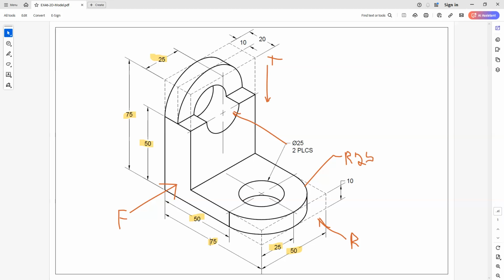And this is one of those other rules of anytime you're doing some kind of drafting, is that you don't really want to waste a lot of time putting double dimensions and dual dimensions and things of that nature. As you can see, by leaving that dimension off, it keeps the drawing a lot cleaner, right? So we don't have to go ahead and specify that stuff. The people that are fabricating these things are smart enough to be able to figure that out. They've been used to looking at blueprint drawings for most of their careers, so they can look at this and go, oh yeah, that's simple enough to build. I know what that is. So when they do their layout, that's going to be something that they can figure out without any problem, or call the drafter or designer and say, hey, what did you mean by this? So they're able to figure that out.